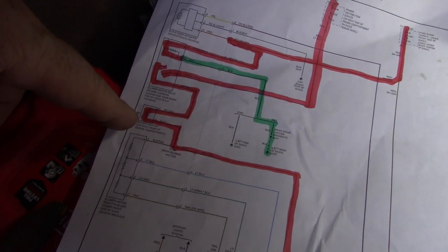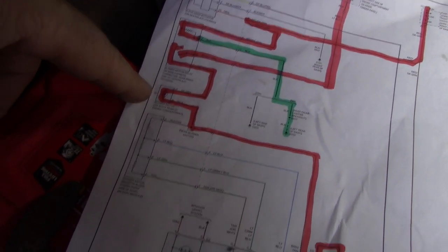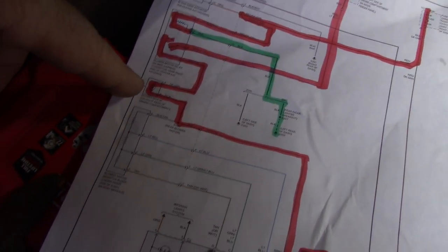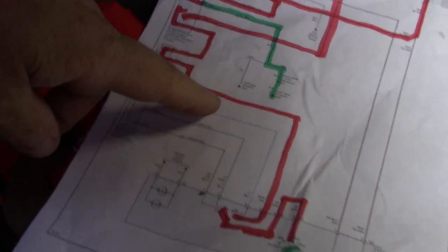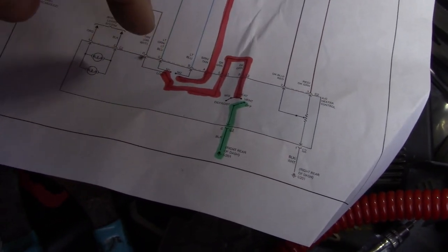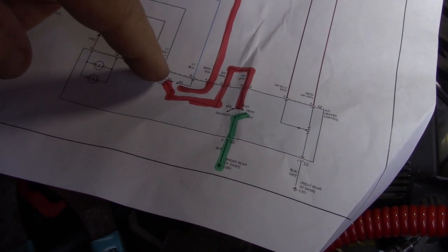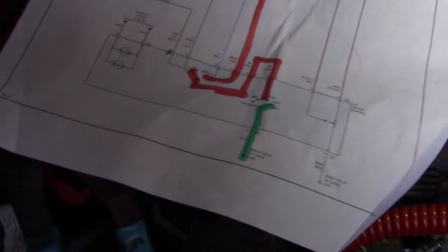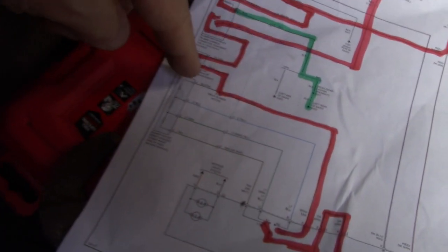But you saw where the blower motor was. It's in behind the battery. It's a pain in the butt to get to. So where's the next easiest place to check? If you follow this along, it would be at the control switch. If we don't have power here, then you're losing it somewhere between here and here. But if we have power here, we know the motor's good because you have continuity through the motor.